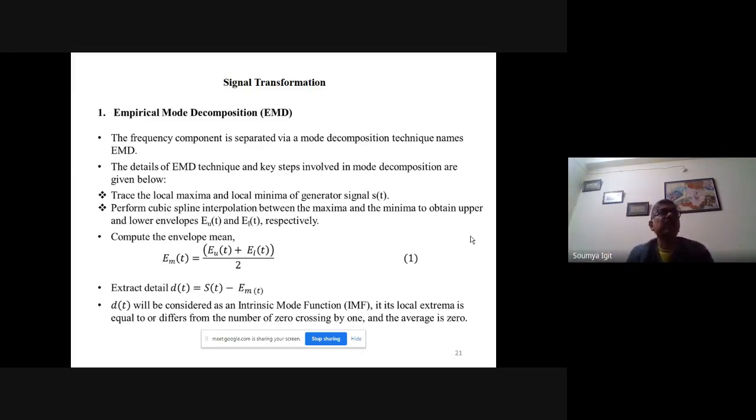It may not be possible when you solve this total second order differential equation, which is non-homogeneous and nonlinear in fact. If you have 2 generators, your aggregation is very simple, but you have a lot of generators being deployed in an integrated power network. And it is not only that, at the particular time scale, the samples that you have taken into consideration at that time, the coherency may get varied. So it is as good as the dynamic coherency.